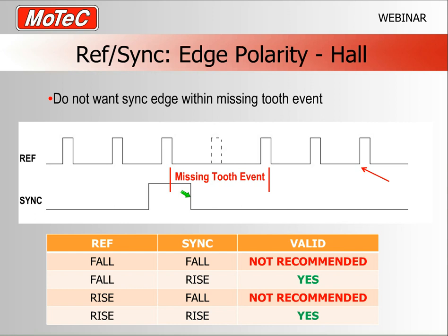So you can see there I've said for the sync in my little table, for both the syncs with the falling edge, it's not recommended. I say not recommended as in it will work and it may not cause problems, but in practicality I would say don't do it, because it can cause you a few issues.